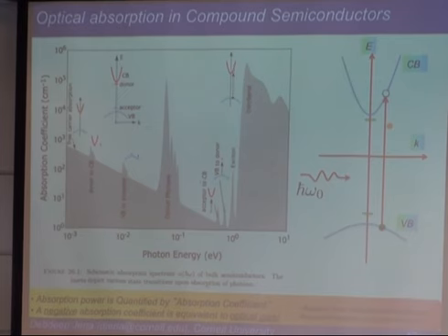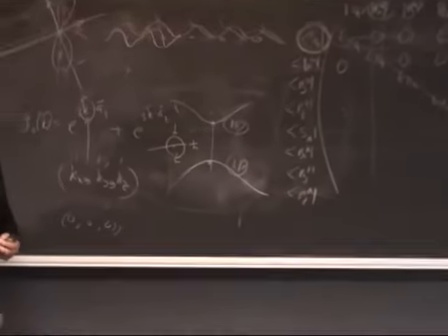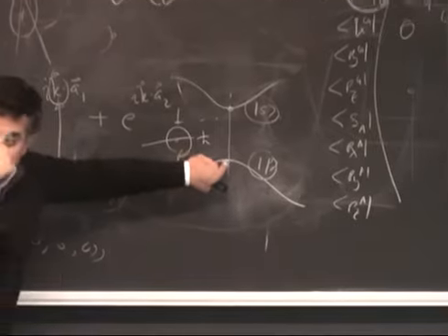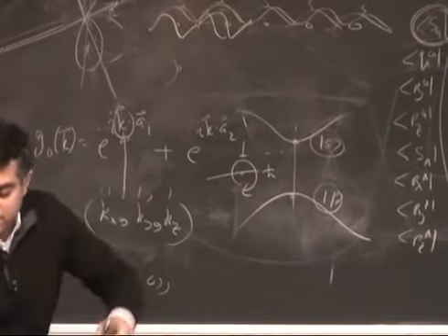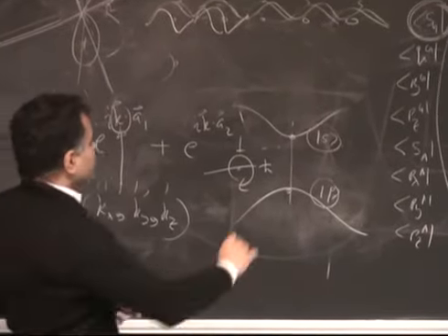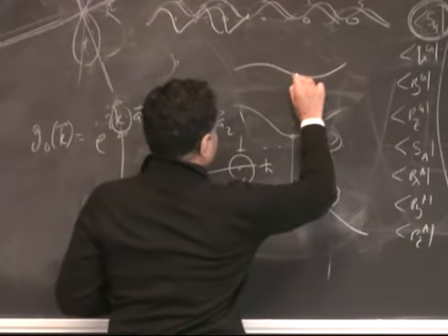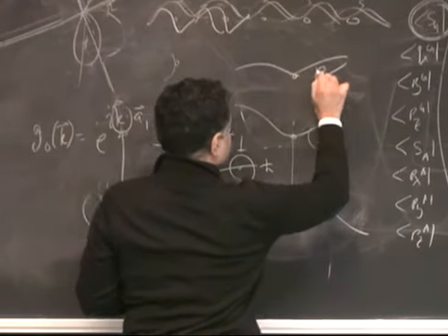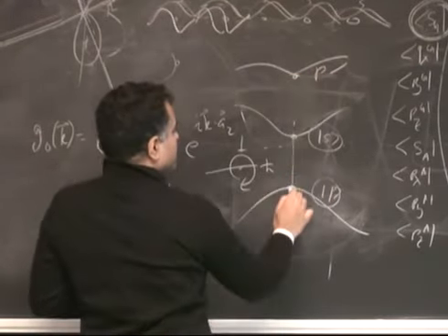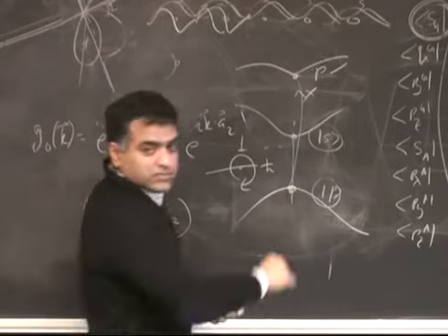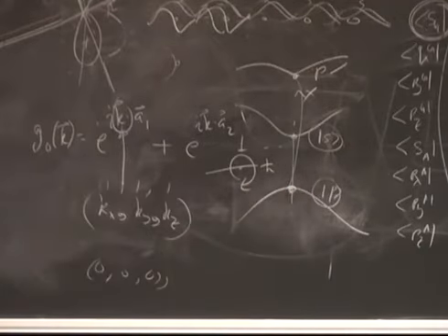And the reason it can do it is because the photon that comes in has an angular momentum of exactly h bar, and what we can show later in the course is if you go from a p orbital to an s orbital, the difference in angular momentum is exactly h bar. And that's why it is allowed. It's an allowed transition from here to there. Going by that argument, if you go to the higher p conduction band orbital here, that's also p, as we just saw. This is p, that's p. This transition will not be allowed optically. Okay, good.